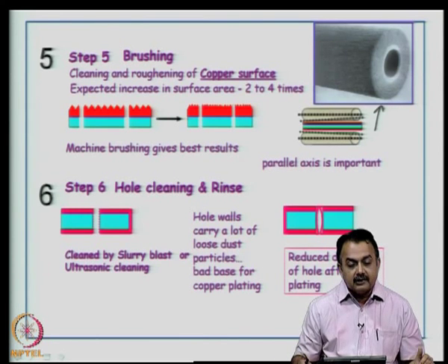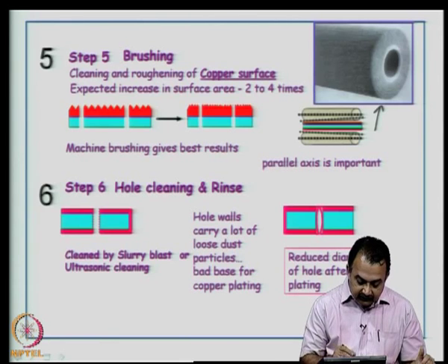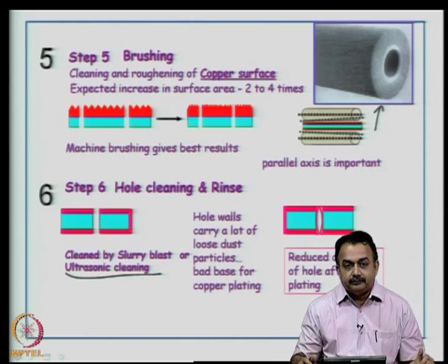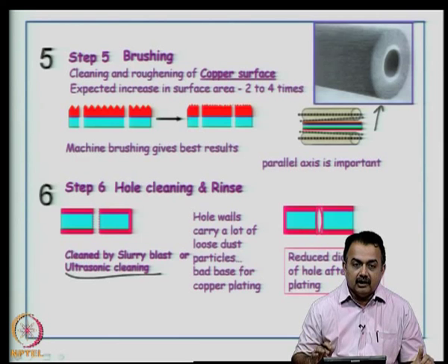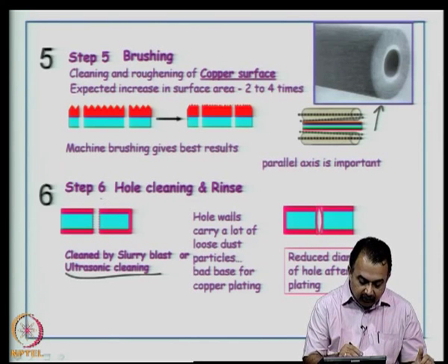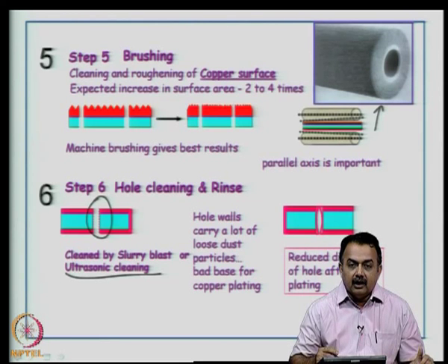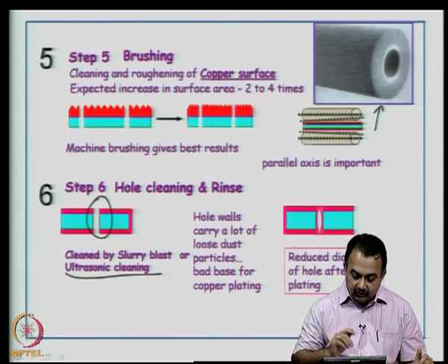The next step is the hole has to be cleaned to take up plating. So, as I said, you can use ultrasonic cleaning, where you can use a mild acid, or you can combine both mechanical brushing and chemical cleaning to make sure that the hole wall is perfectly cylindrical and devoid of all debris, glass fiber, epoxy smear and so on.